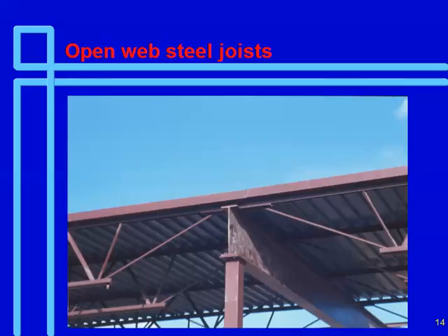and beam. This beam, think of the axial load as being up here. All of a sudden you have a column that has a little thin web going up. You don't have the same L over R, okay? The other thing, and I've been mentioning this when I do some lectures on the 2005 spec, is that we often as engineers forget the basic assumptions involved in the equations we use.